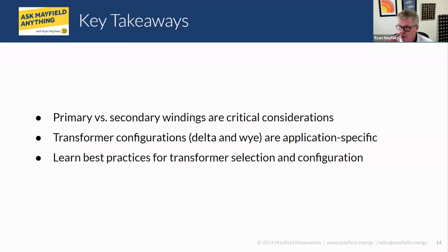Great. Our equipment usually provides phase loss monitoring, which are fairly small and inexpensive devices that we would add to our equipment to sense the phase loss and trip the corresponding device, whether that be a breaker or contactor, to disconnect the system and not allow it to work unbalanced. Also, the electronics will do the sensing and make sure that all 3 phases on the transformers are present.